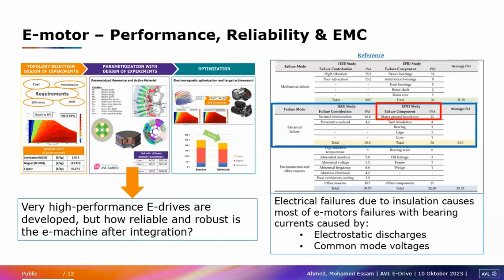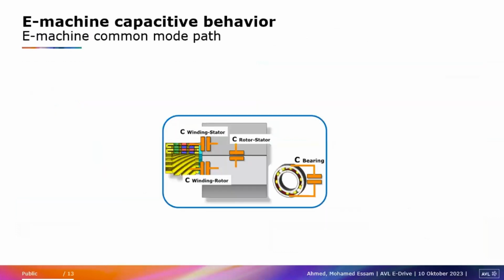So, very good investment. I will not say which OEM, but yeah, we had to tear down everything, the axle, the EDU, and the issue was in the bearing. So after vehicle integration, the E-machine was with some housing, some more loads, it was affecting the capacitance of the bearing, and it was discharging. So the bearing was failing much earlier, after 80 kilometers.